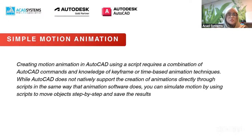We will go to our main topic for today, which is simple motion animation. Creating motion animation in AutoCAD using a script requires a combination of AutoCAD commands and knowledge of keyframe or time-based animation techniques. While AutoCAD does not natively support the creation of animation directly through script in the same way that animation software does, you can simulate motion by using script to move objects step by step and save the result after that.